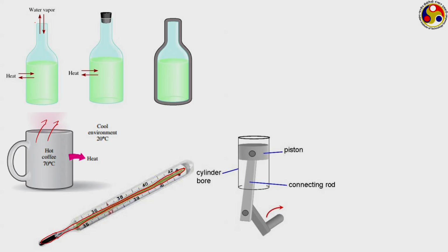What about this one? You have a piston cylinder arrangement, where because of the connecting rod, the piston is continuously moving inside the cylinder. So, we have to choose our system now to analyze the thermodynamic behavior of the gas which is enclosed in this cylinder. Your choice of system can be something like this: the side walls plus the top of the piston plus the cylinder head together can form the system. This is a real boundary that we are using, but a movable boundary, because the piston is continuously moving up and down.